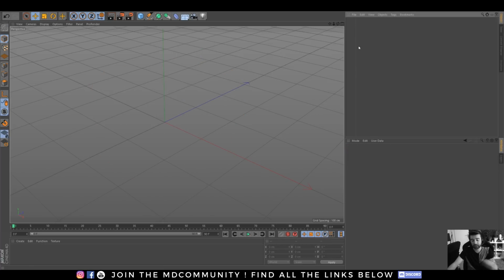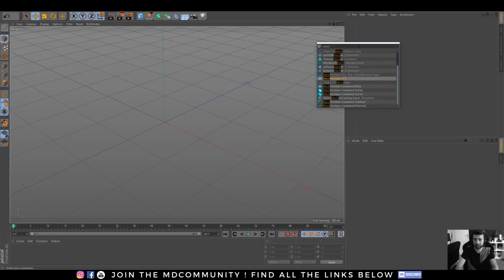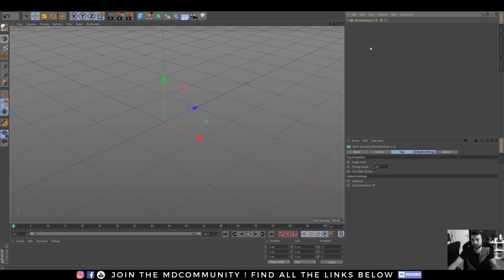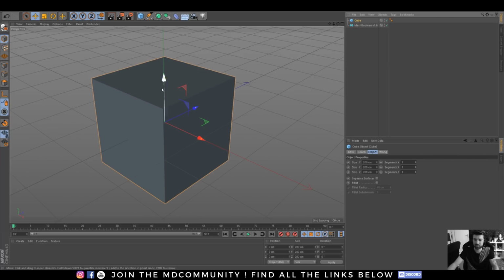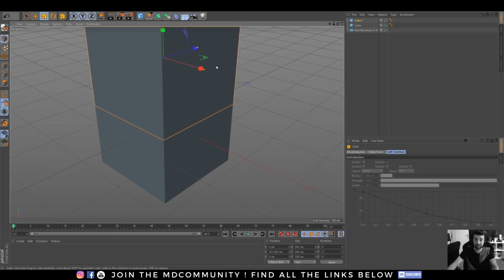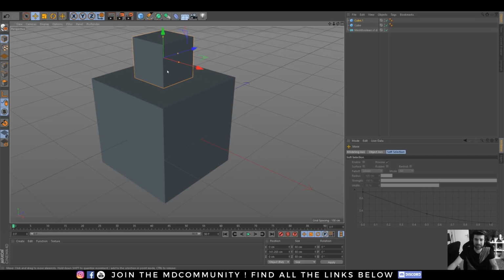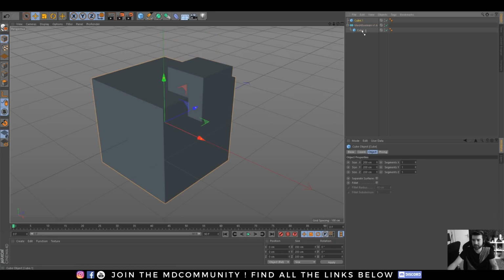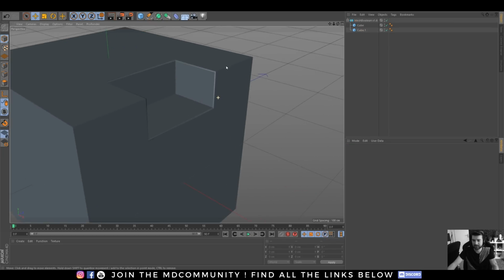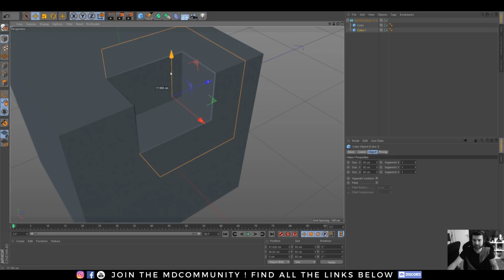So let's take a look at one plugin called Mesh Boolean. It's like the Bool tool from Cinema 4D, but you will have more options. It's the exact same tool, but with the basic needs. Like, see, I have my two objects. Drag and drop it, and you see I have this nice bevel, and it's following.